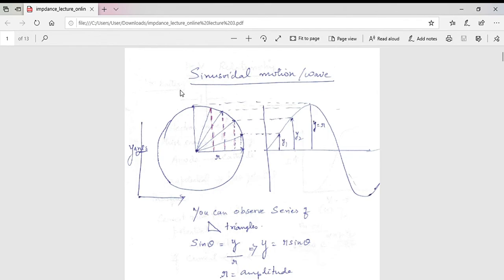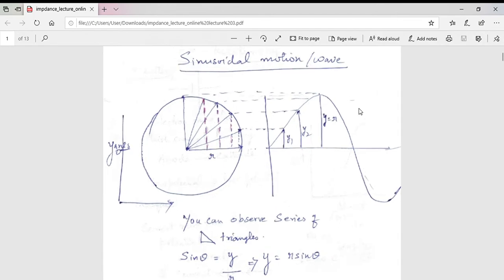On the x-axis, there are various forms in which impedance spectroscopy is represented, but basically here we will apply a voltage waveform at different frequencies, ranging from a megahertz to millihertz or microhertz, and see the impedance response of the given circuit. So it is the impedance versus the frequency of the voltage waveform. That's the spectroscopy. Before entering into impedance spectroscopy, let's understand certain basics which are needed if you want to comprehend the data that I am going to show on impedance.